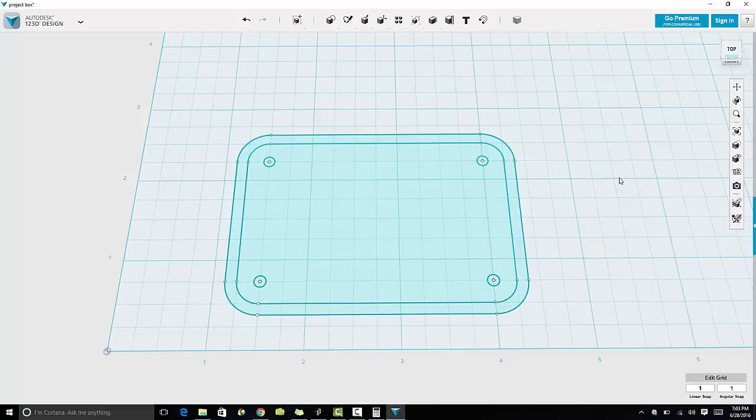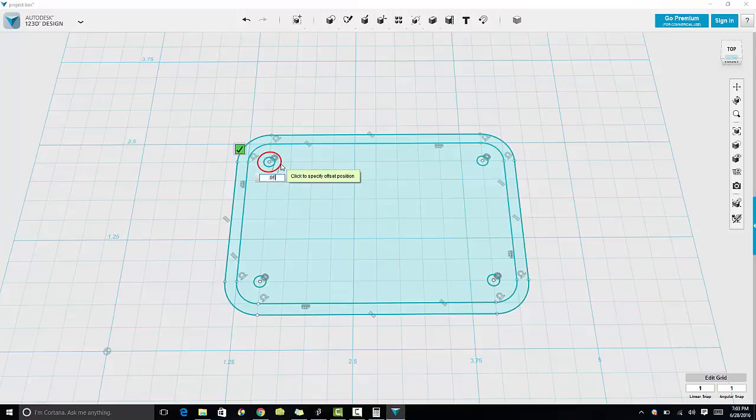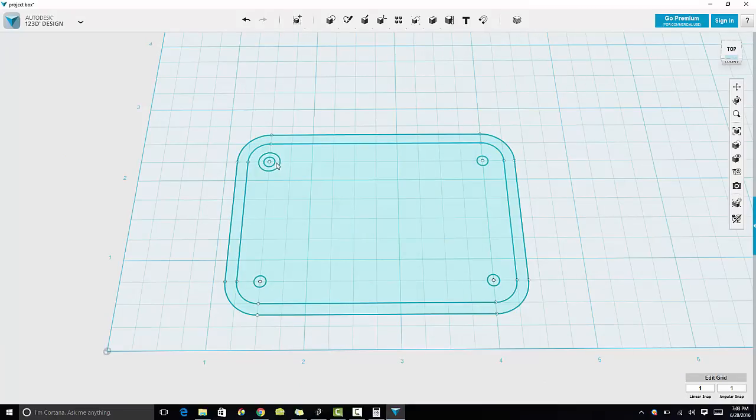The next thing we need to do is create the walls for our standoffs. Another simple thing to do, easily accomplished with the offset command. So this we kind of have to gauge and find out what we want our thickness to be. I think I'm going to go with 0.06. That seems to be a nice number to offset by. Remember, that's how thick our walls are going to be. Too much thinner and those things might bust right off. Remember, we're going to be tapping these holes. So when we go through and tap them, we need to have a nice bond between the surfaces.